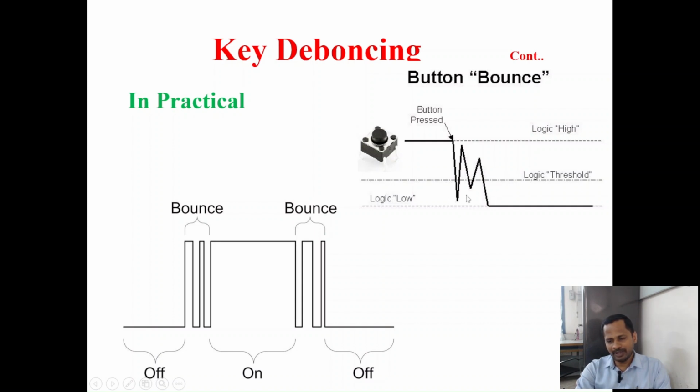If I make this delay, your microcontroller is not going to respond to the bounces, so by default it considers the count as 1. Or you can use an external capacitance to avoid this key bouncing, but that is costlier than the software. So normally the programmer adopts these kinds of techniques to avoid the key debouncing effect.